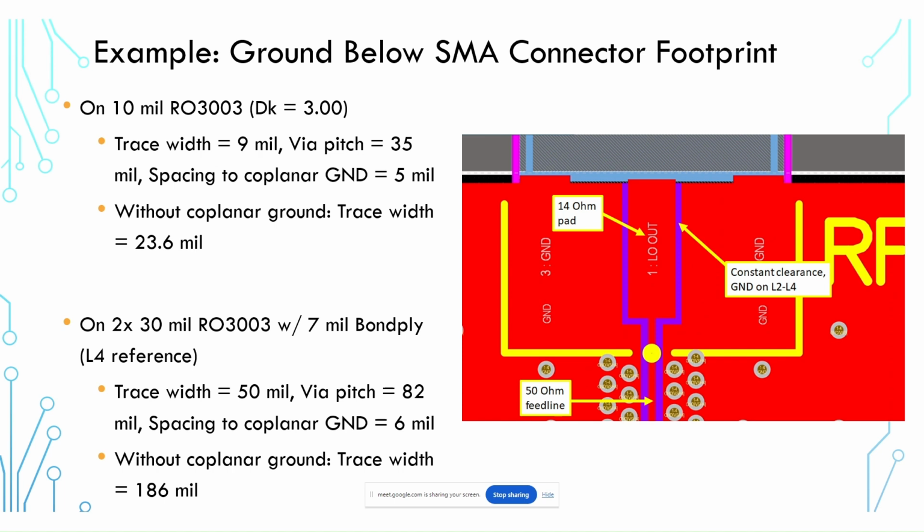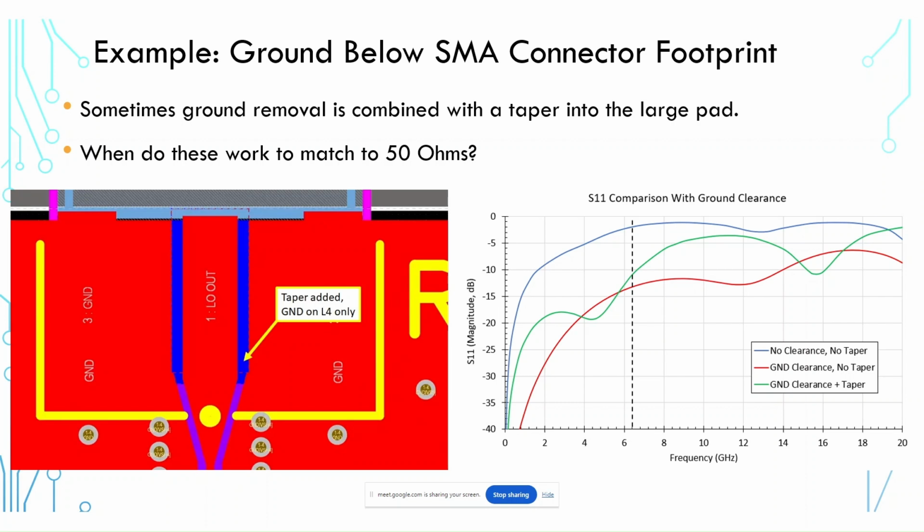What's the easiest way to overcome that? Well, we could do a few different things. We could apply a taper. We could apply a taper and a ground cutout, or we could try to do some kind of impedance matching network. I strongly recommend against trying the impedance matching network because there are much simpler solutions, such as just adding in this taper or providing some ground cutout here.